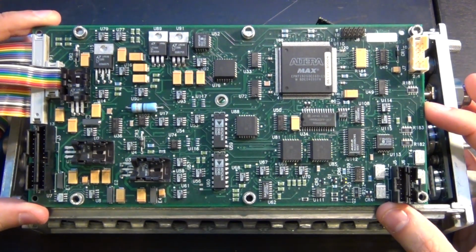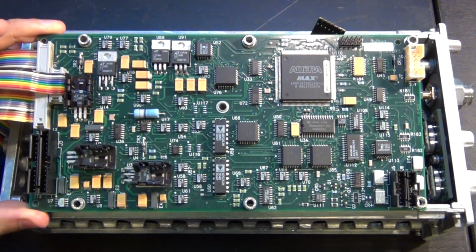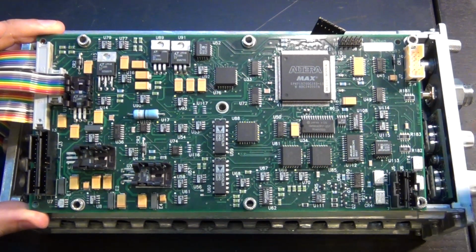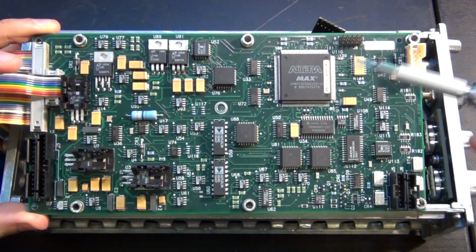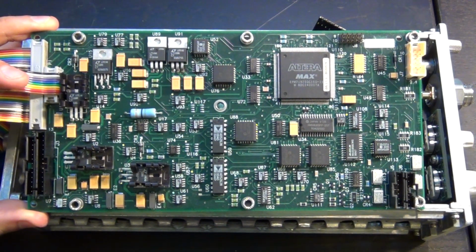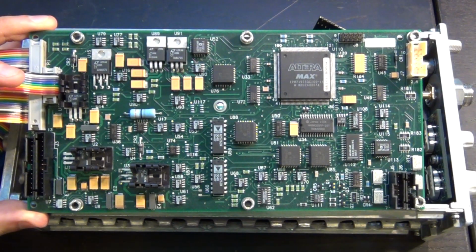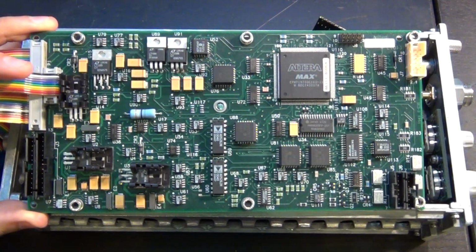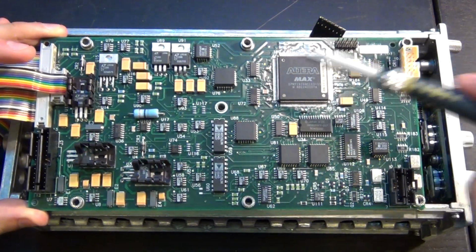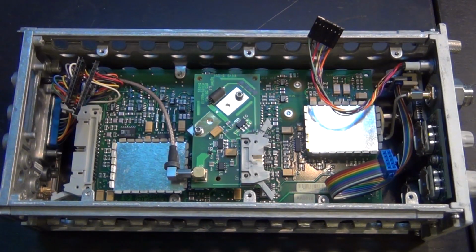This is mostly a digital interface board to the actual mainframe. There's an Altera MAX FPGA on it, which, if I remember correctly, the MAX series was a flash-based FPGA. So this is flash, not an SRAM-based one. If I remember correctly, you can correct me if I'm wrong on that. And there's a bunch of other components, nothing interesting, a whole bunch of DC power conditioning, voltage regulators, and so on. And this is some kind of firmware, obviously, that they can update as they need it.